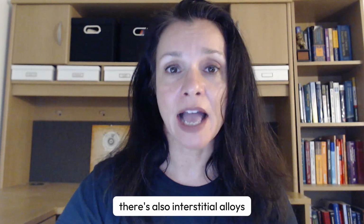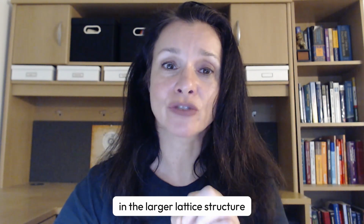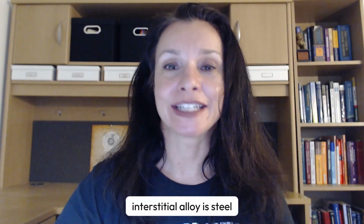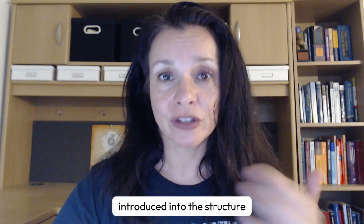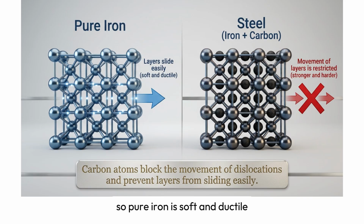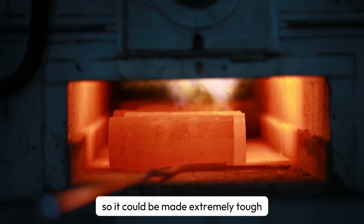There's also interstitial alloys, and this is where smaller atoms actually fit into the spaces in the larger lattice structure. A really important interstitial alloy is steel. And this is because the carbon atoms are small enough to fit between the iron atoms in the iron lattice. And even a small amount of carbon introduced into the structure, like less than 2%, can change the properties of iron dramatically. So pure iron is soft and ductile. Steel is hard and strong. And this does depend on the carbon content and the heat treatment. So it can be made extremely tough.